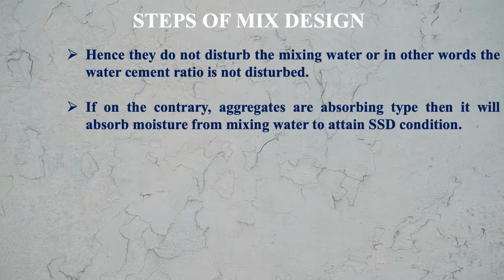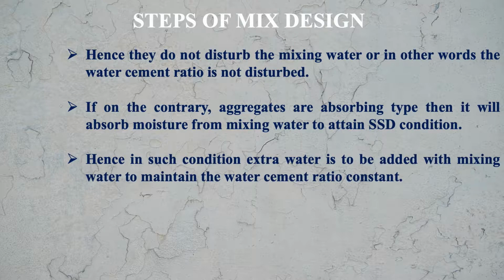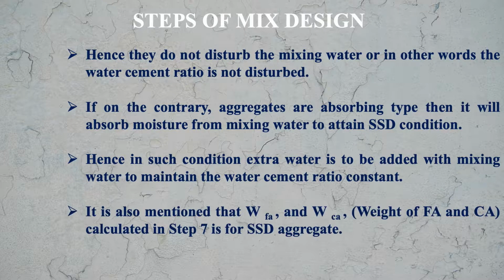If on the contrary aggregates are absorbing type, then it will absorb moisture from mixing water to attain SSD condition. Hence, in such condition, extra water is to be added with mixing water to maintain the water cement ratio constant. It is also mentioned that